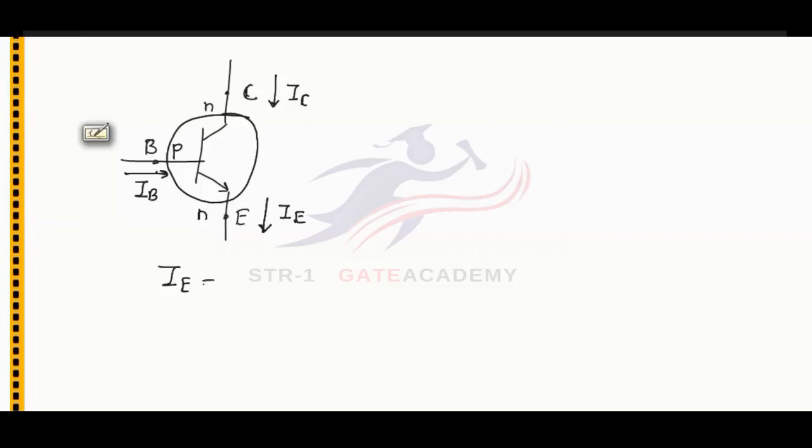For this transistor, the actual direction of emitter current IE will be in this, and collector current will flow in this direction, while base current will flow in this direction. If we consider this BJT as a junction, then total outgoing current should be equal to total incoming current. According to KCL equation, total outgoing current, that is IE, should be equal to total incoming current, that is IB plus IC.